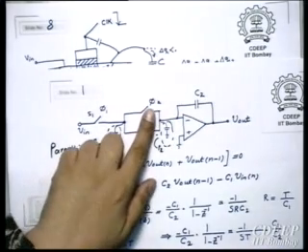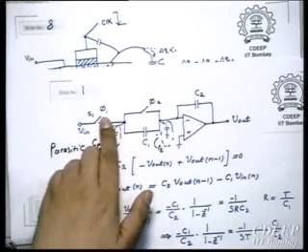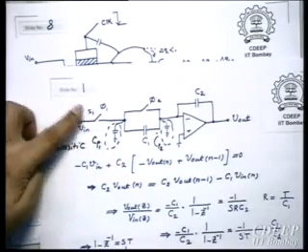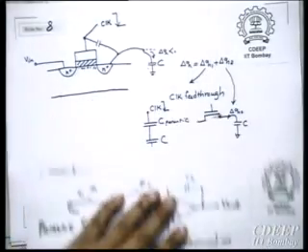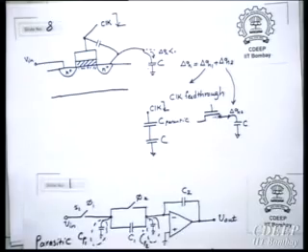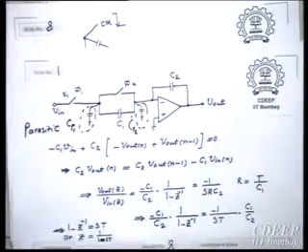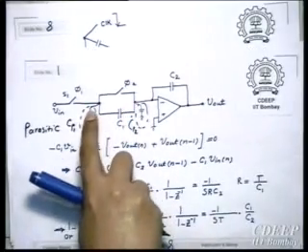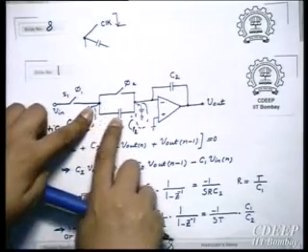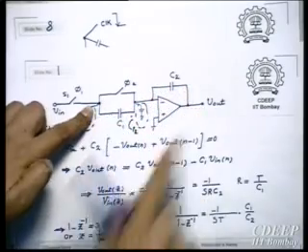So still phi 2 is not operating. These two are non-overlapping phases. Therefore, when this S1 opens, this phenomenon happens: clock feedthrough and charge distribution, in fact charge feedthrough from the channel. This charge feedthrough will change this voltage, and some part of it will come here, and then will go into C2 and then be out.